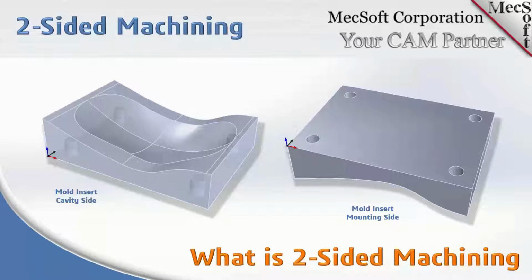This first slide we have up is just a simple understanding of what is two-sided machining. Basically, if you have a feature on the opposite side that you have to machine, then obviously it's two-sided machining. And you may want to consider how you're going to machine that. If you're definitely going to machine it on the CNC, then obviously you have to flip it over and do a second setup.